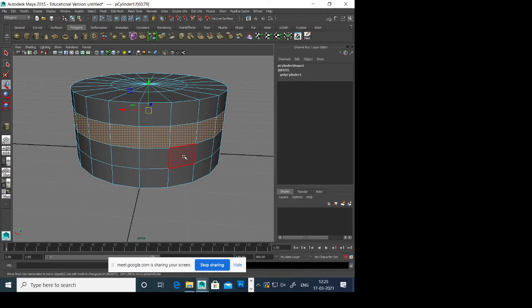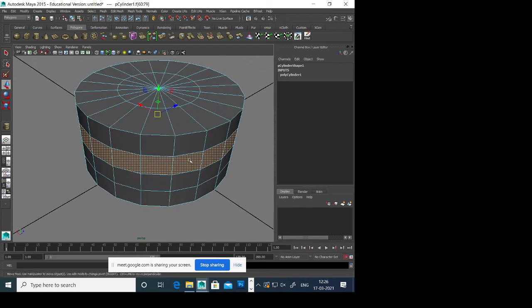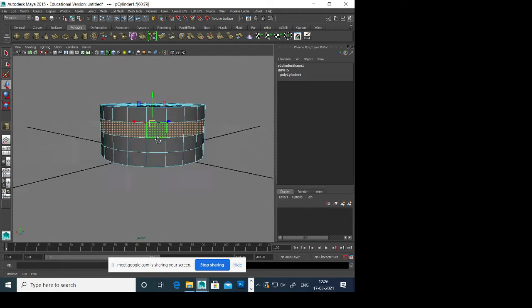And in the Maya 2020 version, the layout has an automatic layout option. The automatic layout works beautifully. It almost lays out the entire UV like we do it manually, right? So 90%, or around 70%, it will fix everything and lay out the entire UV, and then whatever you want to modify, you can just manually modify that section. So it saves a lot of time there. So UV is super fast in Maya.